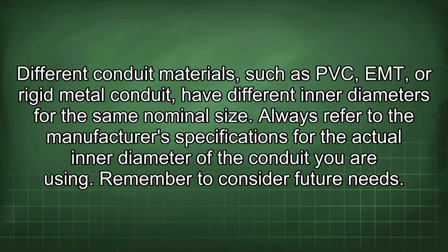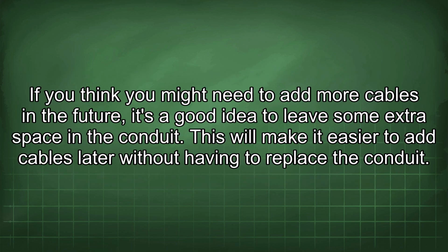Always refer to the manufacturer's specifications for the actual inner diameter of the conduit you are using. Remember to consider future needs. If you think you might need to add more cables in the future, it's a good idea to leave some extra space in the conduit. This will make it easier to add cables later without having to replace the conduit.